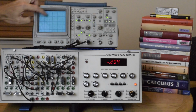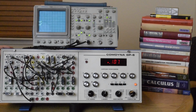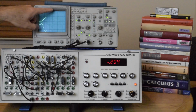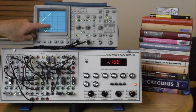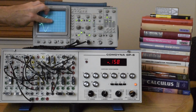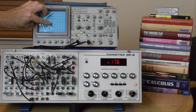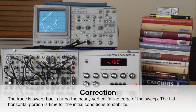But channel 1 is actually looking at that internally generated sweep signal, which represents the computer time. So that's just a linear ramp from effectively -10 to +10 volts. But then the y-axis is the actual problem solution, or the output of the analog computer. And you see they're both synced up to start at the same time. There's a little bit of a delay between the end of one solution and the beginning of the other, which is just the time for the sweep to sweep back, basically, and for the initial conditions to stabilize.